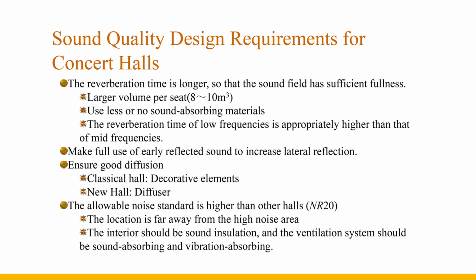The second, make full use of the early reflected sound to make it evenly distributed in the auditorium to ensure sufficient loudness and intimacy. Increase the lateral reflection to obtain a sense of surround. The third, ensure good diffusion. Classical halls use decorative components and new halls should use diffusers. The fifth, the audible noise standard is higher than other halls, and the noise evaluation index is below NR20.